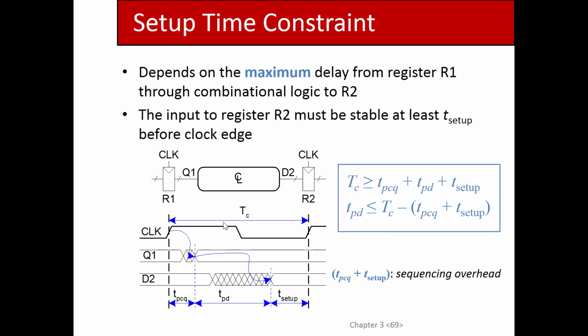So this is the worst case propagation delay. You have to add up the propagation delay of all of the logic gates connected in here serially, along the longest delay path. You guys with me? You have to trace every path through here. And then you have to add the setup time, because that's the extra margin you need. The propagation delay at this point has to arrive before the setup time.